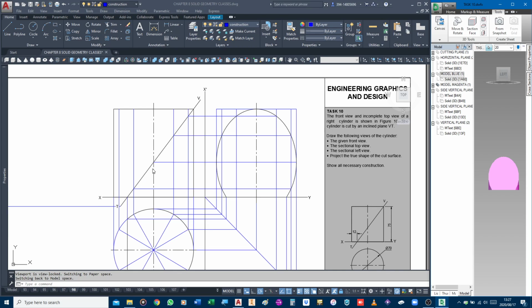If I look at this here again, remember I didn't use numbers this time. If I look from the cutting plane to the base at the bottom, that is what stays. Which means that line will be dark, that line will be dark, as well as the base, because the base is from there to the edge. So that's going to be solid.